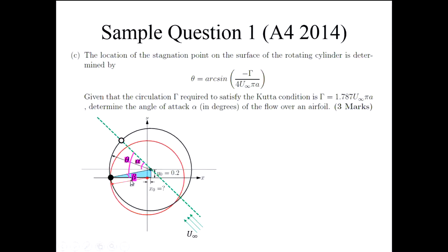So we need to rotate that amount to account for this geometry property. So beta is just this small angle, directly related to y naught, which can be used to calculate the camber of the airfoil. And theta is just the total amount the stagnation point has to be moved for it to go back to the critical point. Any other questions?